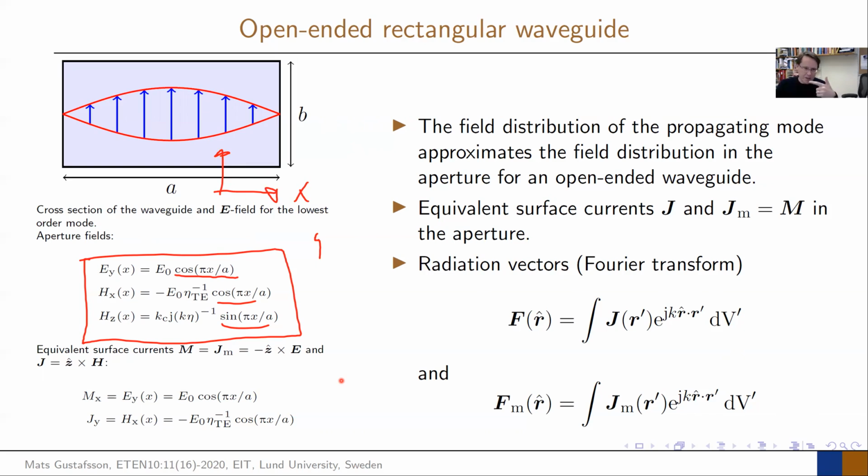Let's then think back to your Fourier transform. If you take the Fourier transform in the smooth direction, you would have low side lobes. If you take the Fourier transform in the direction where you have a discontinuity, you would have higher side lobes. Think back 2, 4, 5 slides. I showed you the radiation pattern from the horn antenna. That's exactly what you saw. So that comes from this mode structure inside of these rectangular apertures in some ways.